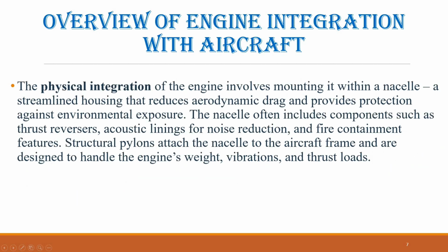The physical integration of the engine involves mounting it within a nacelle, a streamlined housing that reduces aerodynamic drag and provides protection against environmental exposure. The nacelle often includes components such as thrust reversers, acoustic linings for noise reduction, and fire containment features. Structural pylons attach the nacelle to the aircraft frame and are designed to handle the engine's weight, vibrations, and thrust loads.